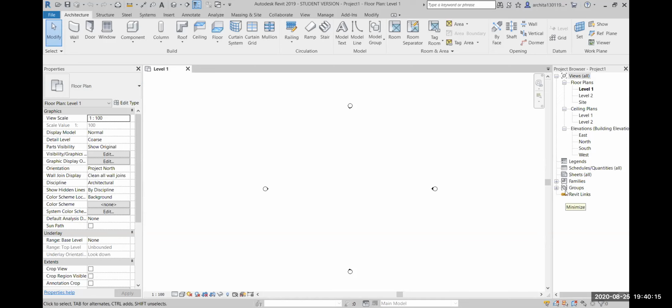Share the image with me. I'm sure you're missing something, because it's very simple. If you have created the extrusion and everything, you just have to correctly select the extrusion and then give it a glass material from the side properties panel. Okay, ma'am, I'll try, because my laptop is updating. Can I show you later, ma'am? Yeah, sure, no problem. Thank you.